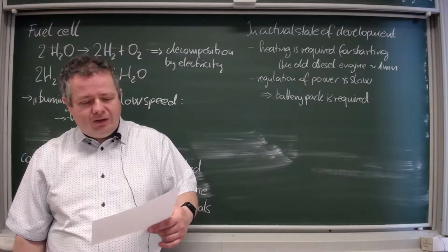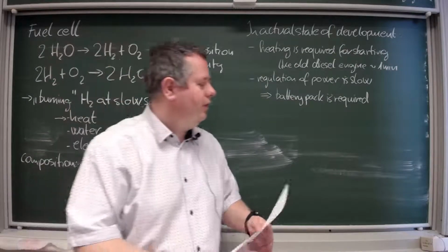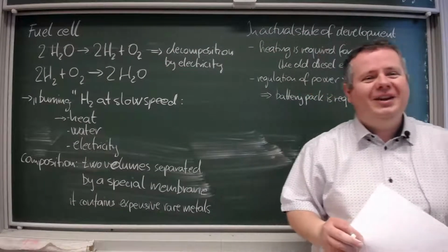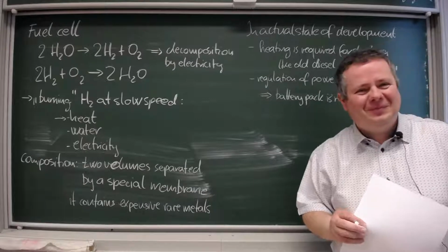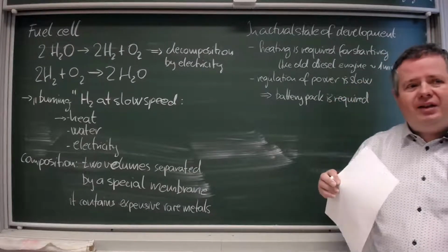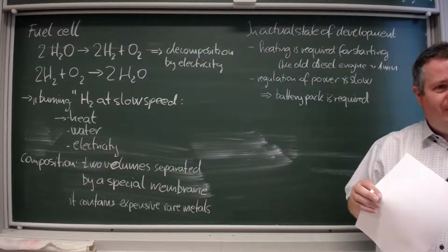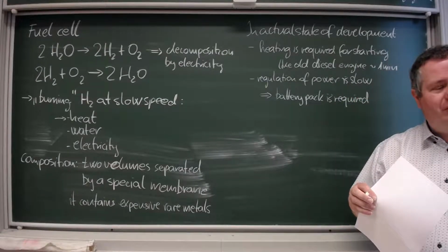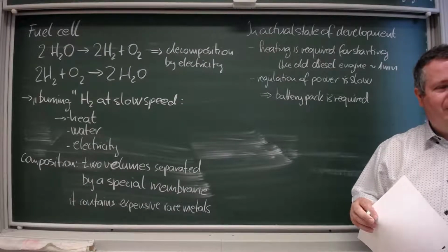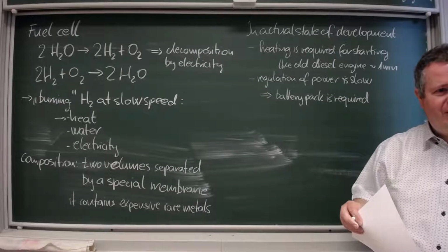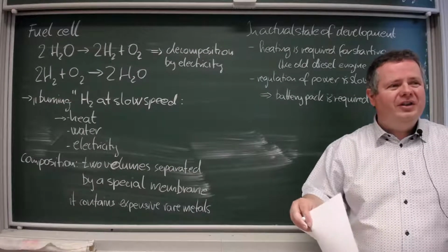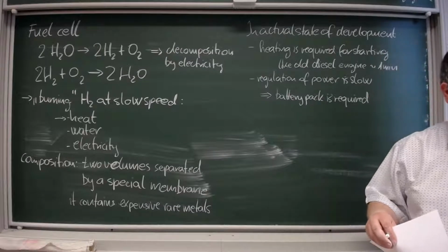So not only the fuel cell is expensive, but also it requires a quite large battery pack with it. When I say large battery pack, it's like in the Toyota Prius. So let's say in the compartment below your rear seat in the car. Not a complete chassis like in a modern electric car, a smaller one. Let's say the surface of your rear seats in the car. That's what is required. Okay?